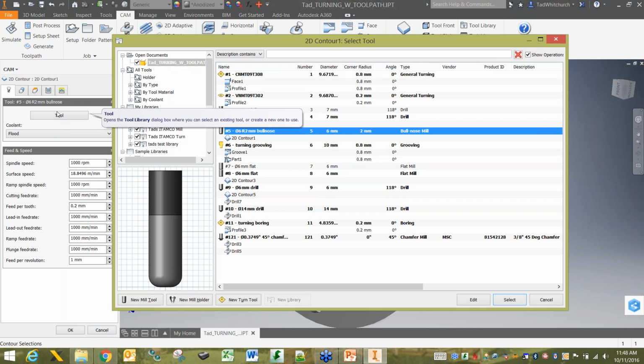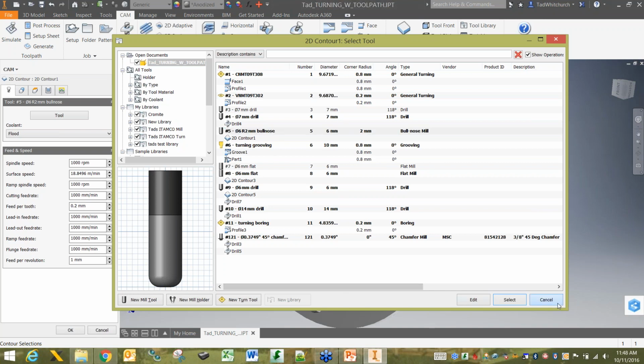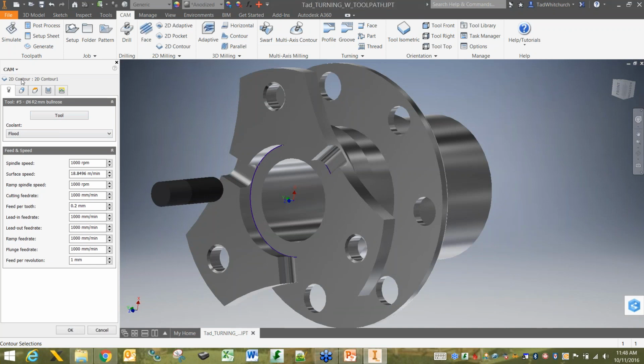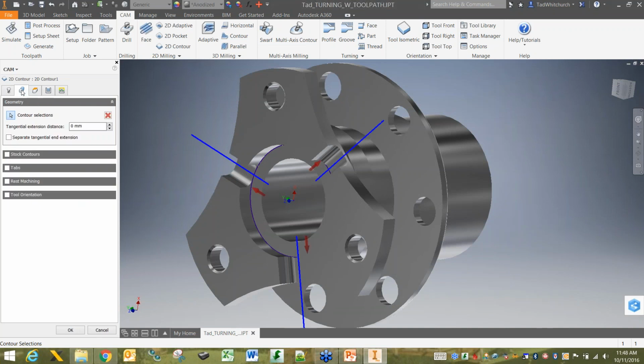Basically, this same type of tool, but there's radiuses on the engineering, how it was engineered. So I'm just going to load an end mill that's got a large corner radius on it. Still doing the contour operation. So again, I'm just selecting the contours. And in this case, I can see I can just pick an edge.